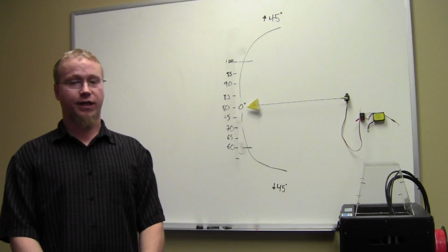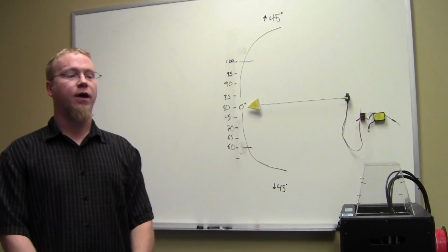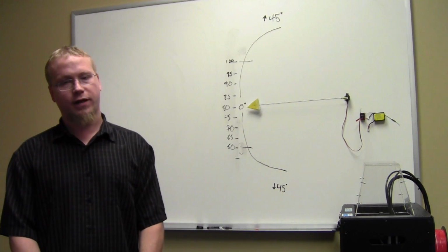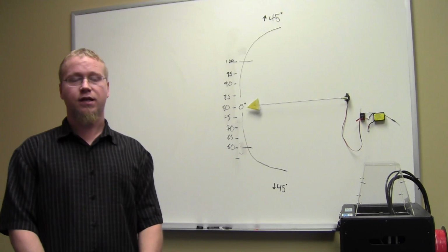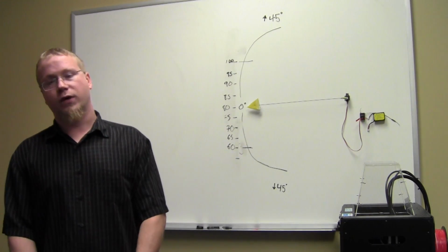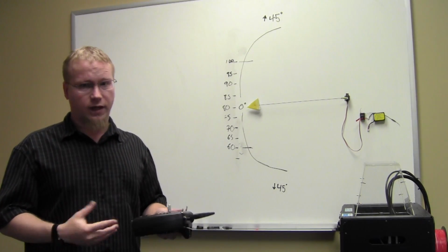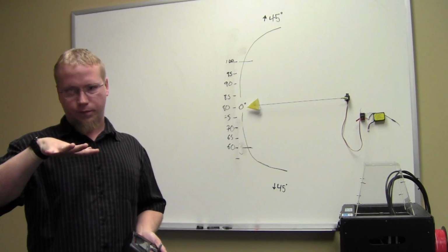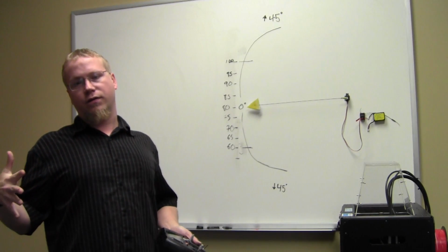Okay, so a little explanation about flight modes. Dual rate is a flight mode. Dual rates and exponential is a flight mode. In this day and age, flight modes, it's used to describe a lot of things. A lot of our safe planes, AS3X planes, they have different flight modes which incorporate the receiver, and what it does is it is listening to a channel on the radio, like the gear channel, to say, okay, we're gonna go into a mode where it stabilizes the plane, right? That's a flight mode, yes, but it's controlled by the receiver.